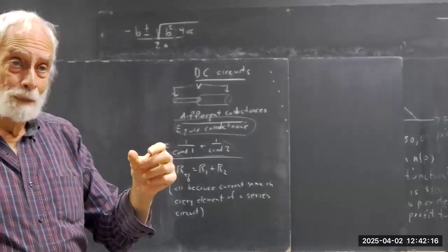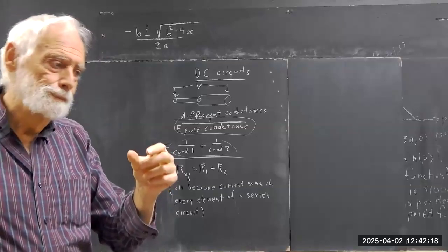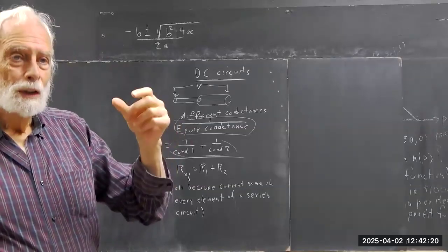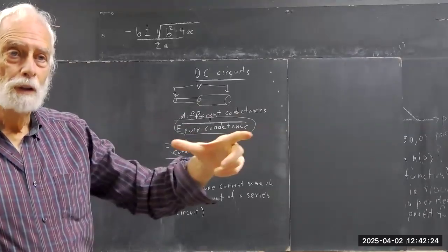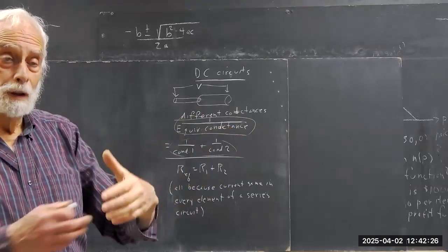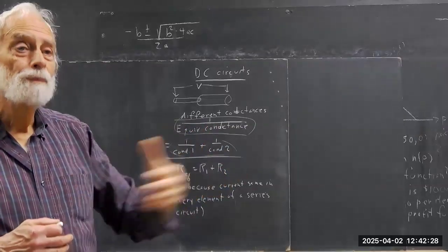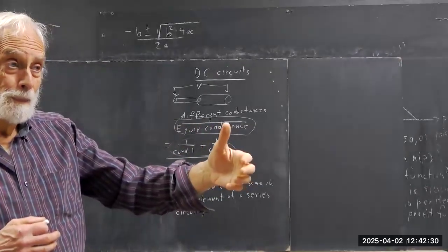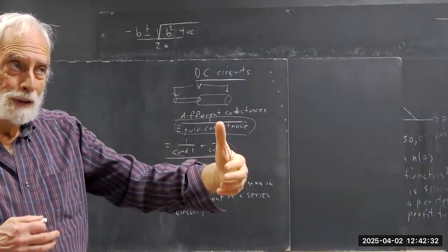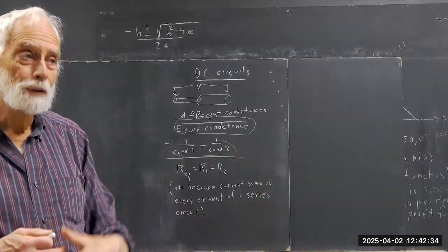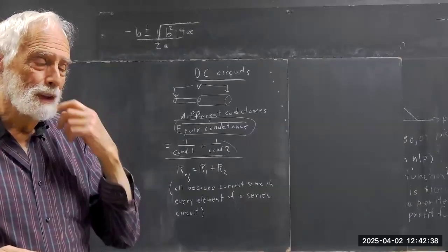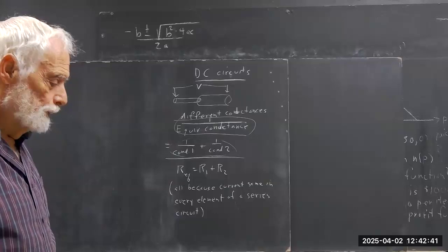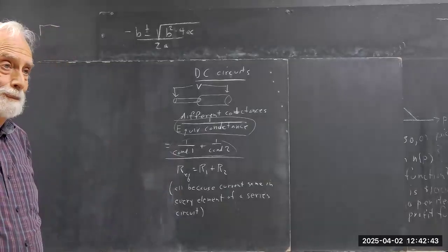So it's short, which means, well, a short cylinder is going to have a lower resistance than a long one. Why? Because the long cylinder spreads the voltage out over a greater distance, and the spread of the voltage is the gradient of the voltage, which is the electric field. Okay? It's actually, the electric field is actually opposite to the gradient.